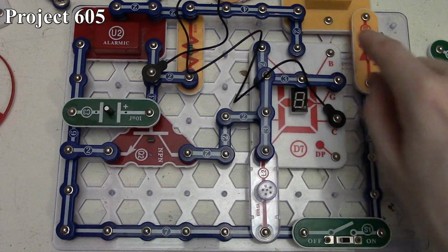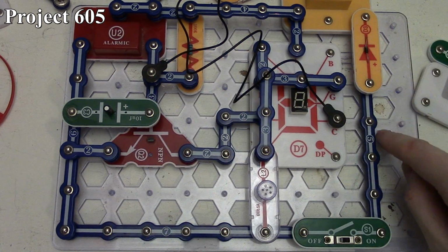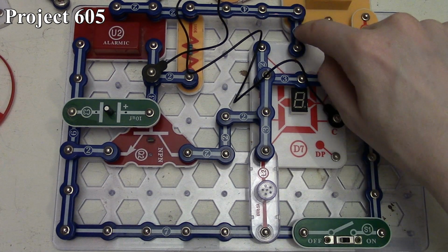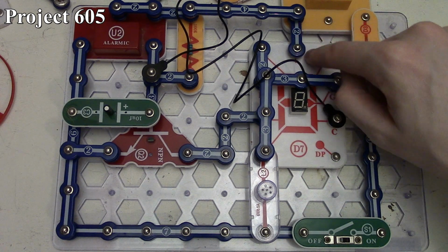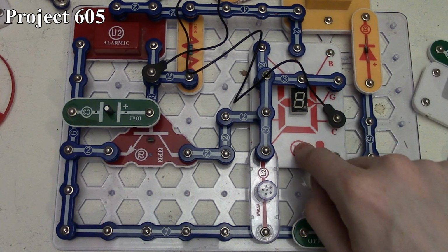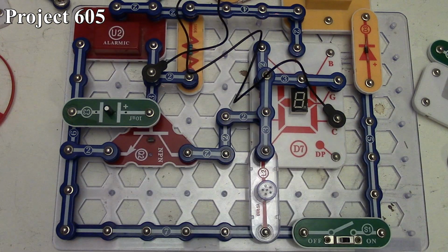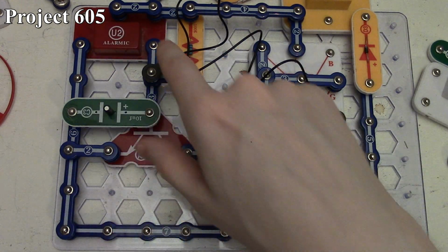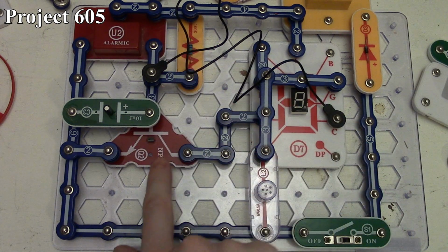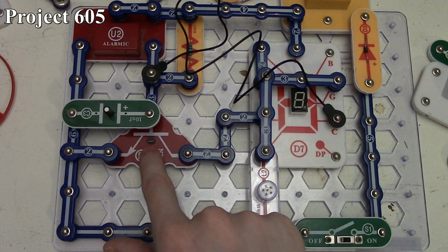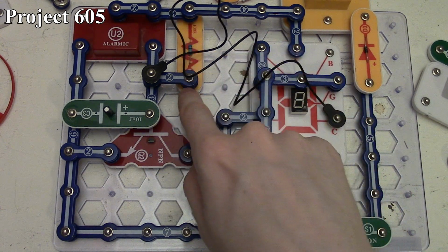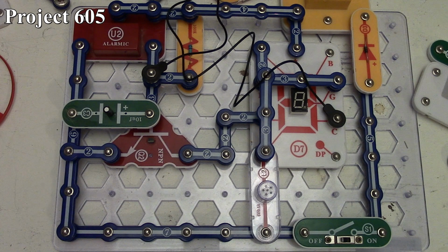So here we've got our 6-volt setup with our diode going into ground, a regular one here. That is then feeding both the positive input of our 7-segment LED here, but also feeding the power input to our alarm IC, which is going to be used for the blinking later. Its output is then driving both the base of our NPN transistor here, along with being brought down some by our 100,000 ohm R5 resistor here.